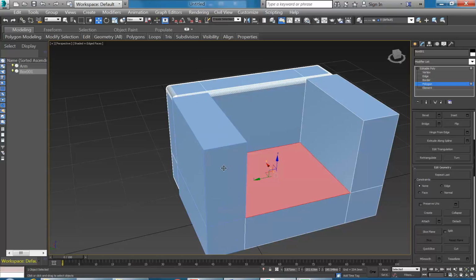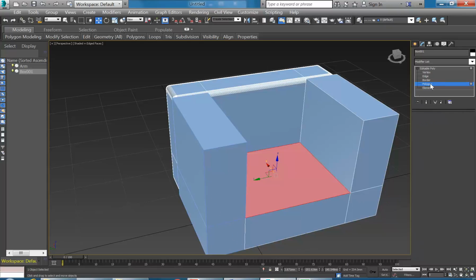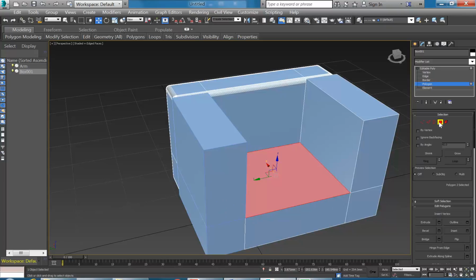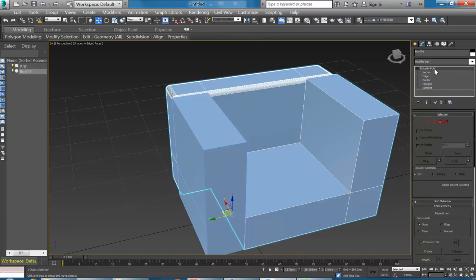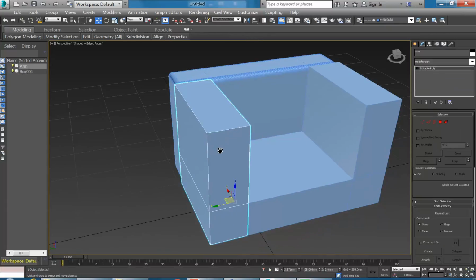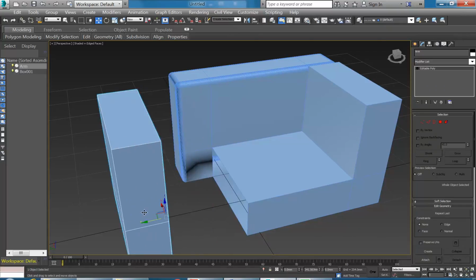So then I can select, so here, notice I'm in sub-object mode, and that's the last major thing I wanted to show you. So there we've got an editable poly, which has these different elements. When any of those are selected, then it's like you're working in sketch mode in Revit. You can only select the parts within it. You just need to click onto one of those buttons, or choose that option editable poly at the top, and then you can select something else. So there's my separate arm piece,